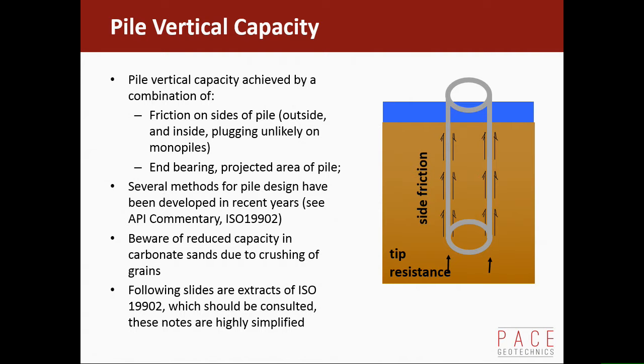It's actually quite rare that piles are truly plugged, and certainly when you're driving them, they're very rarely plugged because you're hammering it in. You basically hammer it in, and that shock wave goes down. The inertia of the plug of soil inside the pile means that it effectively stays where it is. So when you hammer the pile in, you've got to be quite careful that you allow for some of that soil being displaced, so you end up with more soil inside, or the soil in the pile actually comes up over, and you've got to allow for that when you're working out how much pile you have left to stick up, or where your follower is, which is what you put on top of the pile to put the hammer on.